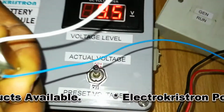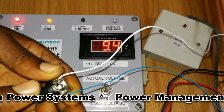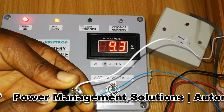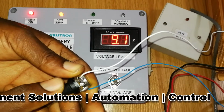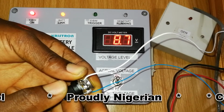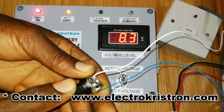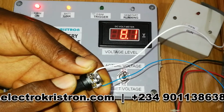Don't forget, this is the actual we're monitoring. The preset remains on 6 volts. You only need to set that once and leave it at that setting. The one that keeps going up and down is the actual, because as you are charging, the battery voltage increases. As you are using, the battery voltage drops.